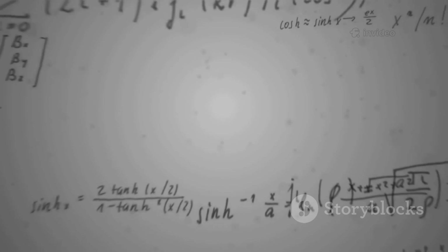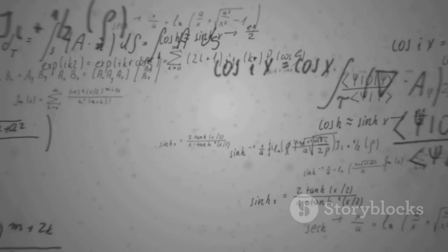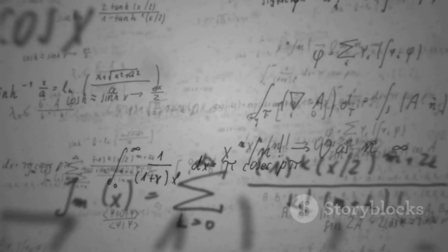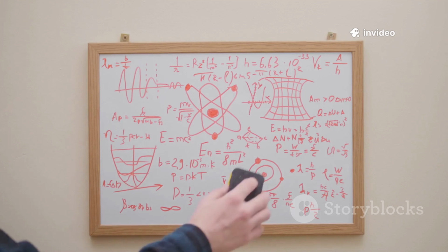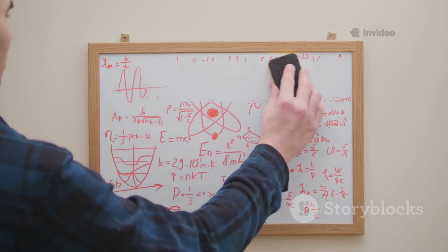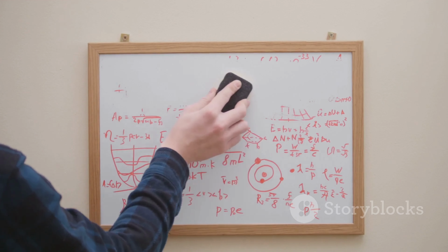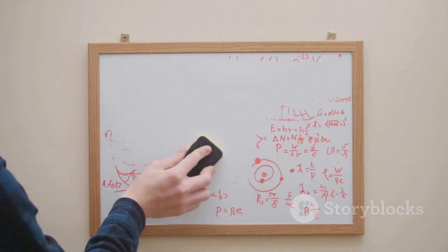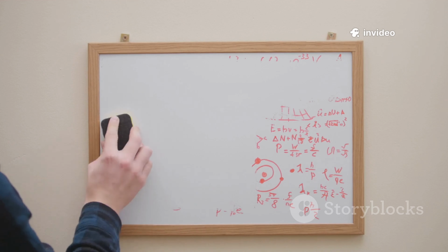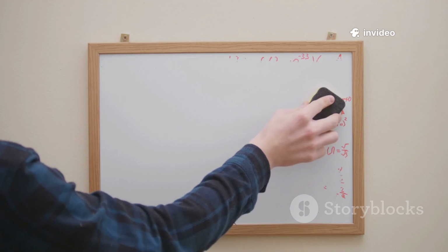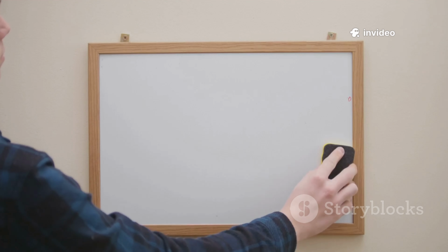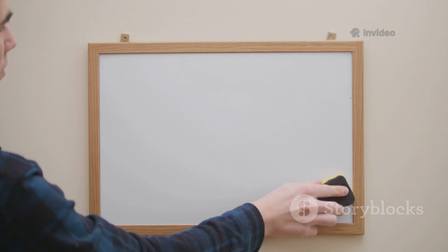The formula for calculating total resistance in a series circuit is straightforward. R_total = R1 + R2 + ..., where you simply add up the individual resistances. The formula for parallel resistance is a bit more complex. 1/R_total = 1/R1 + 1/R2 + .... You need to calculate the reciprocal of each resistance, add them together, and then take the reciprocal of the result to find the total resistance.